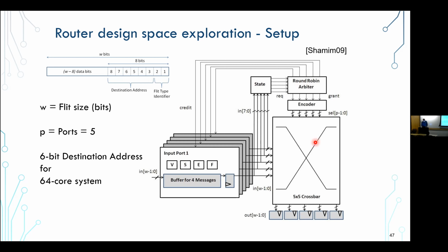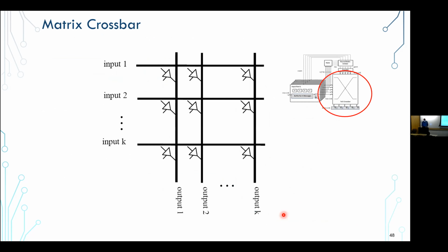And then finally, you have to traverse the crossbar and also buffer things on the output side. Or in this case, we're just doing input VCs, and we're essentially having registers at the other side to latch the data that traverses. So it's really just like a pipeline stage.